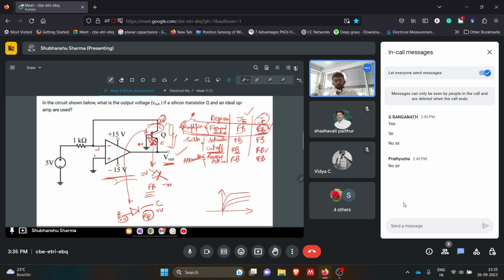So let's say, initially, when we did this configuration, the op amp does not consider its feedback. Let's say there was no feedback, and this was simply acting as a comparator. We have 5 volts here, we have 0 volts here. This is ground, this is 5 volts. Simple, no virtual short. At the moment when we just closed the path for this whole circuit, initially, momentarily, this op amp acts as a comparator. Then this is 5 volts, and this is the inverting terminal, and this is higher than the non-inverting terminal of this op amp. Then what happens?